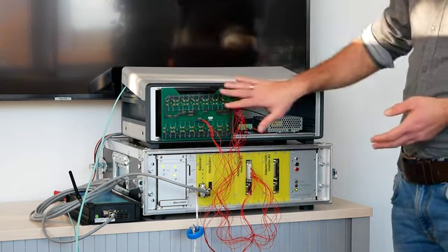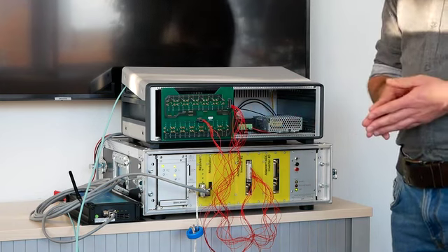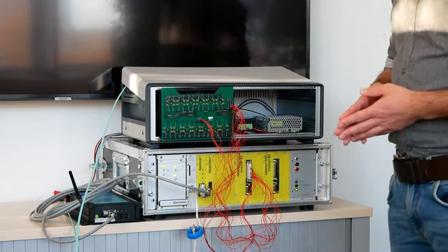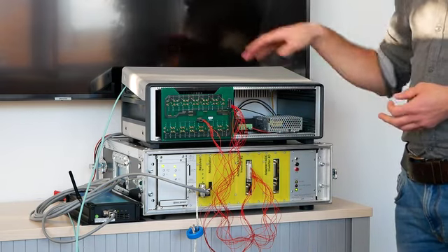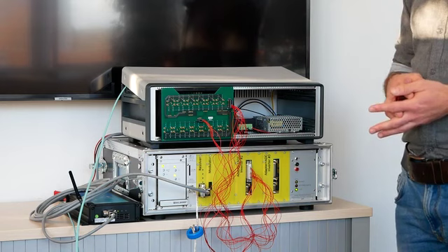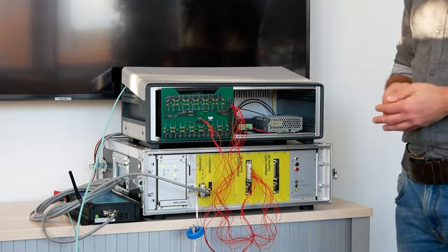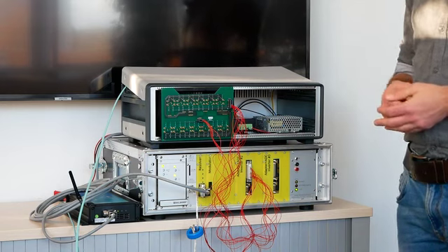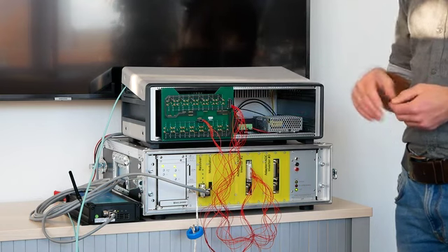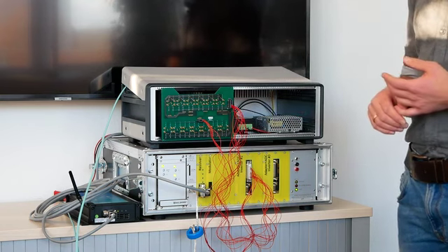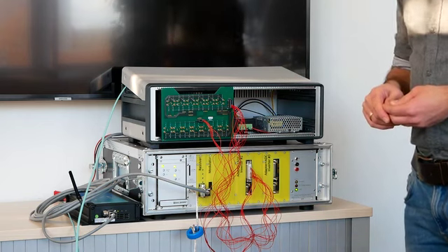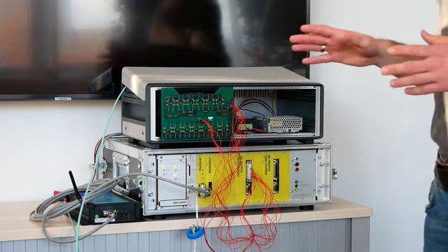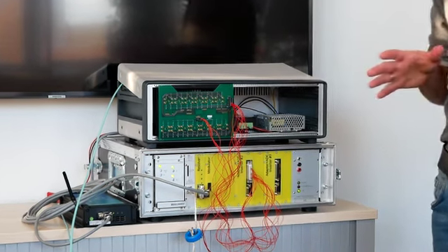What you can see here is a failure injection matrix, which we have in between our FPGA-based emulation system and the unit under test, so that we can freely introduce shorts or opens in each of the signal paths here. We focused mainly in this setup on decentralization.